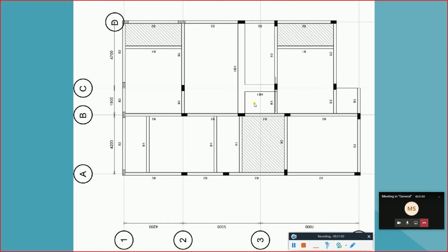So once again, the function of the hidden beam is to reduce the sizes of the slabs, to divide the bigger slab into smaller slabs so they can be designed without the necessity of extra beams and extra columns. It's more expensive than the regular system, but that depends on the customers. A lot of customers don't want to see columns and beams inside their areas.